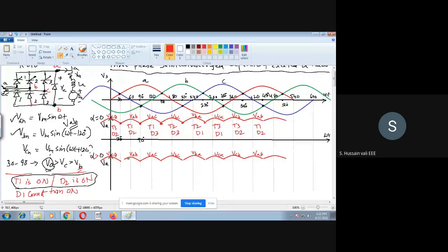You see here, T1 here and T1 here also. Now the T2, I will erase this part. You must understand why I am erasing it: both these are A, whereas both these are B. Then the next one is C, C, C, then once again A. Now you see there is a gap I have given here. At this instant you trigger thyristors 1, 2, 3 respectively. If you don't trigger, there will be a gap. So in this gap, what will happen?